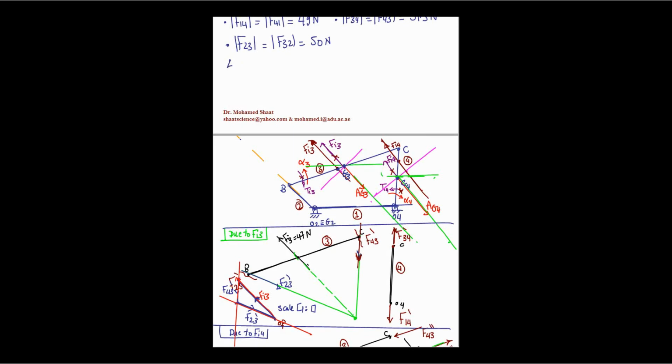So number 4 is going to be the length of the crank. We're going to work on crank number 2 that we skipped at the end, right? This crank should be a two force and couple member, as we discussed before, right? Why? Because this is crank number 2. There should be one reaction force here, and there should be another action force here.